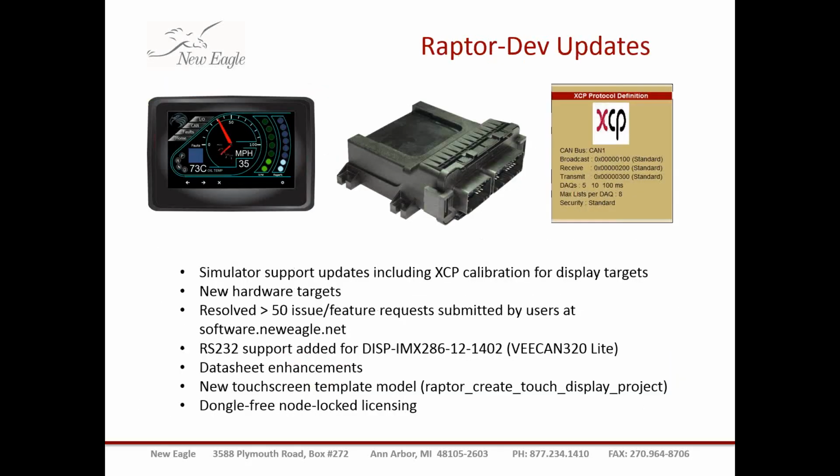A couple of things that we've updated in Raptor Dev lately. We've done some simulator support for our display targets so that you can do XCP calibration. You can do it running the simulator on the PC, and that allows you to really quickly develop your display targets. We've added a few new hardware targets that we'll talk about later.